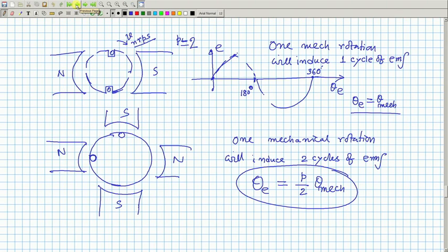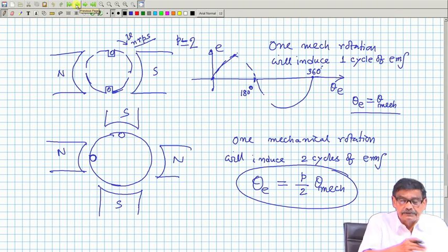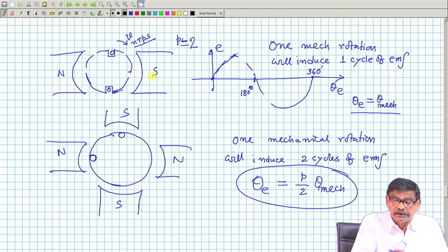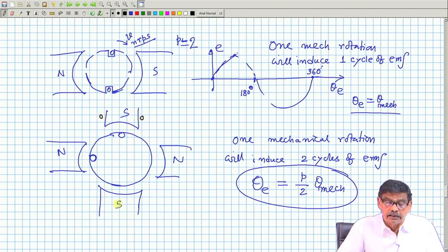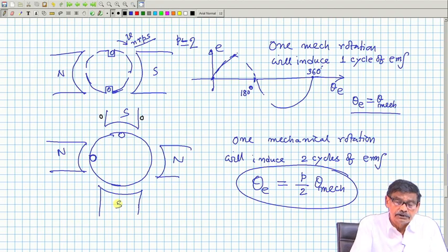that in a DC machine there will be a stator structure which will have projected poles like this, and it could be a 2-pole or multipolar stator. These north south poles will be created by coils which will be put around it. These are called field coils, and on the rotor side there will be an armature.